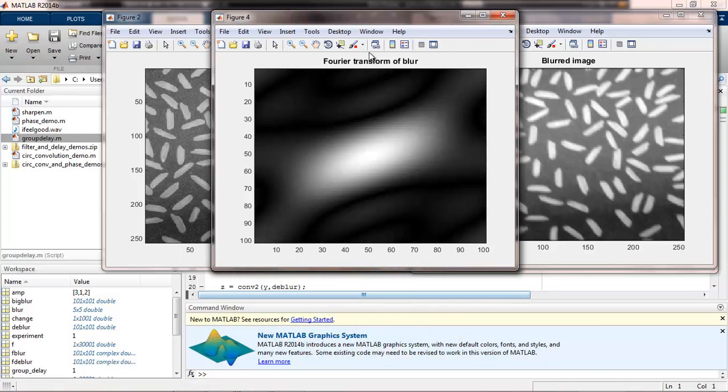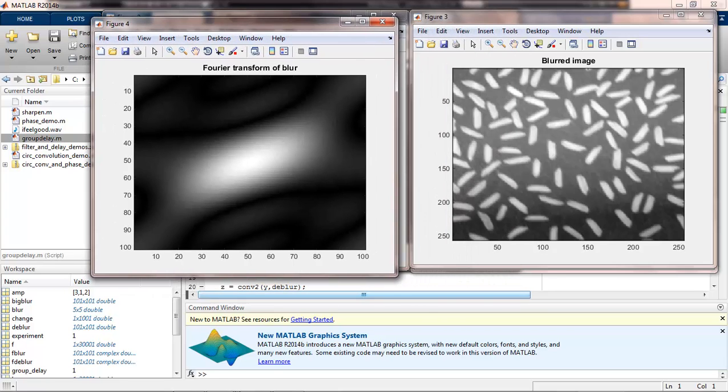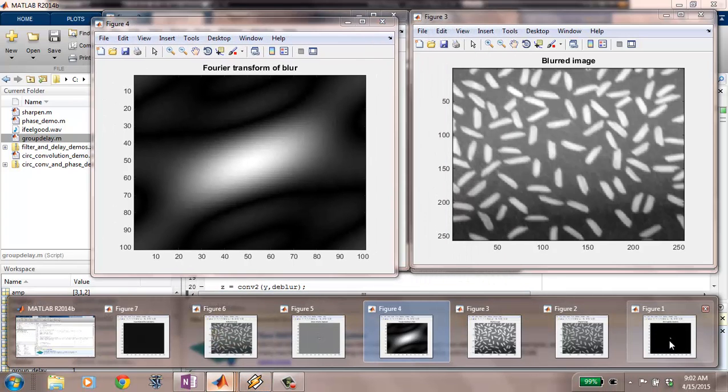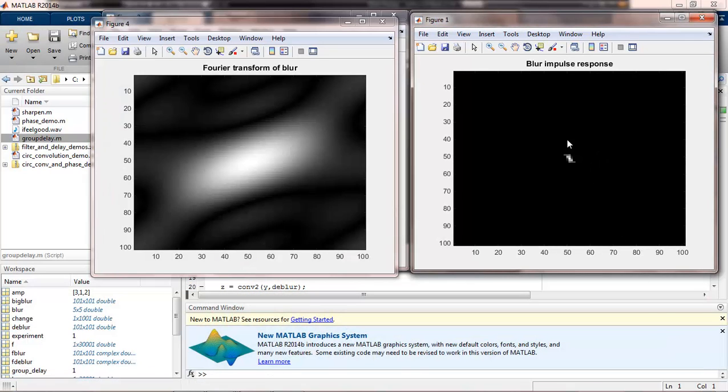So here, what we have is the two-dimensional Fourier transform of our blur process. Here's the impulse response in time. If I do a two-dimensional Fourier transform and just plot the magnitude, this is a plot of the magnitude of the Fourier transform. The center is frequency 0. I've centered it with FFT shift. What this is saying is 1 means those are parts of the frequency domain that are kept, that are passed through this filter, that aren't eliminated. Black being a value of 0 means those frequencies are attenuated, maybe deleted entirely from our image.